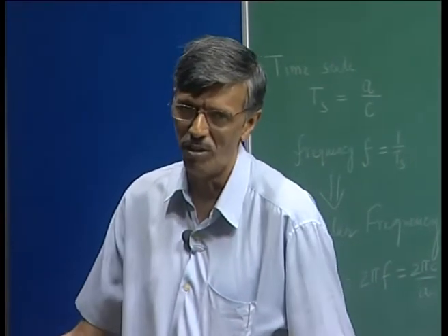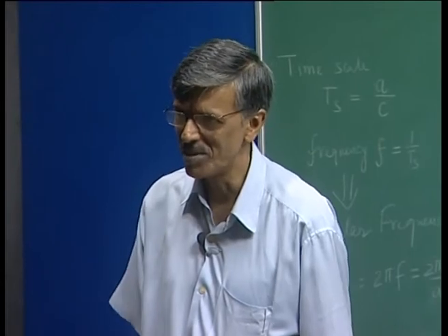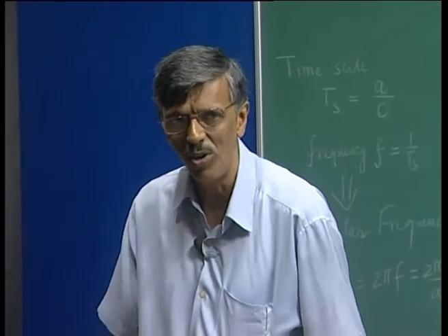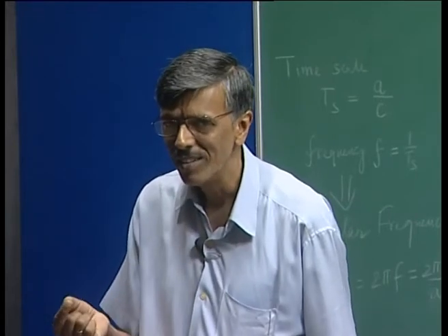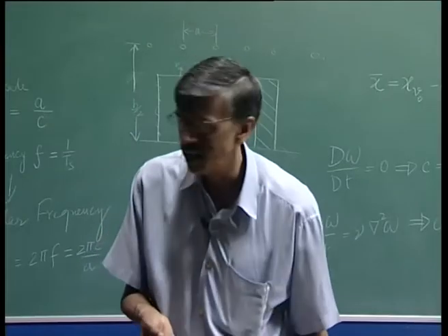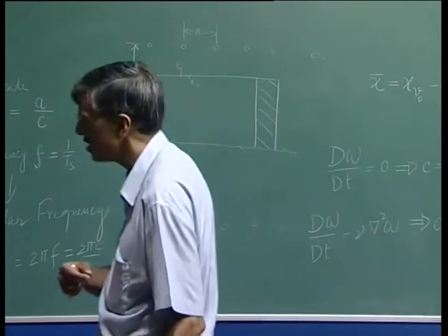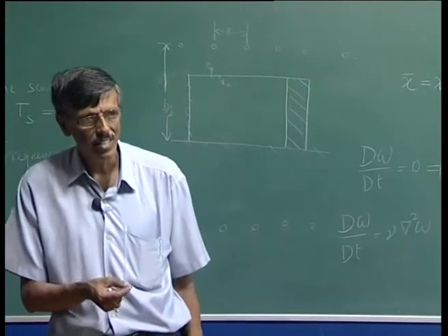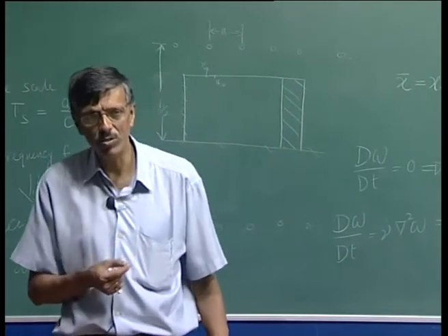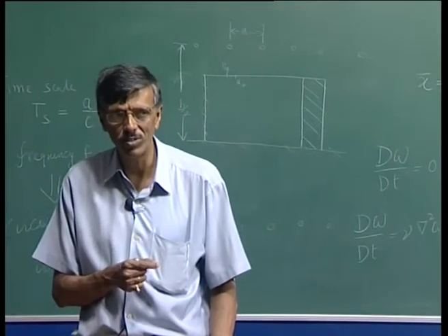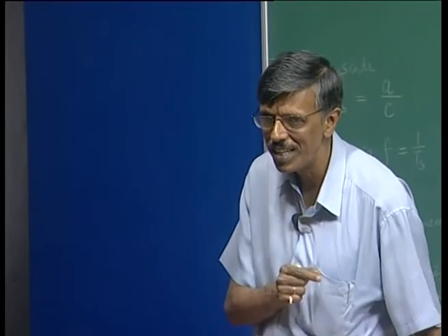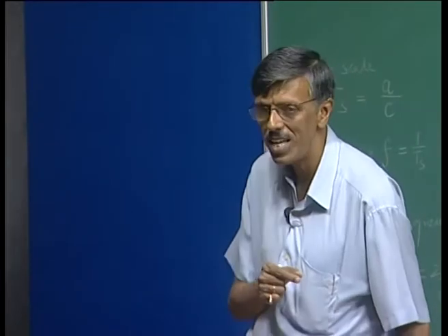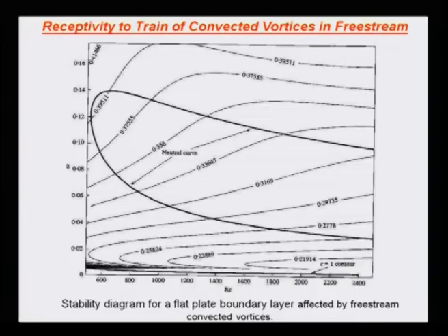I mean, you know, free stream turbulence, etc., they all do have finite visible effect. So what are we missing? We are missing what we discussed today, that those vortices themselves did not necessarily be inviscid vortices, and then C will not be equal to infinity, and different values of C will have different instability pattern.